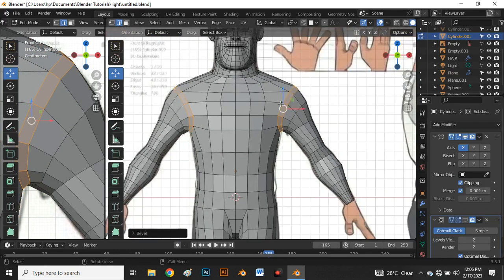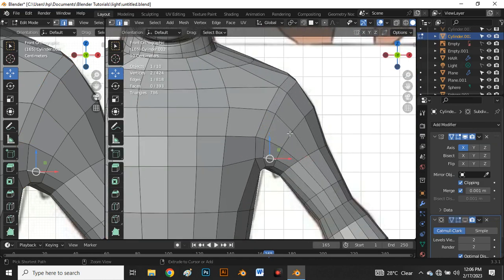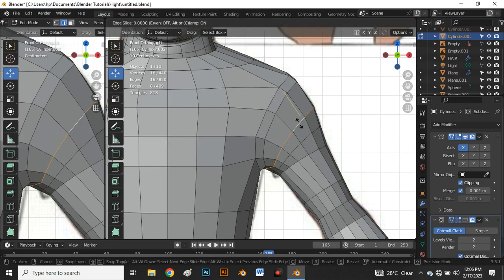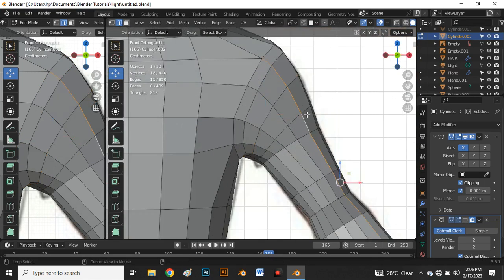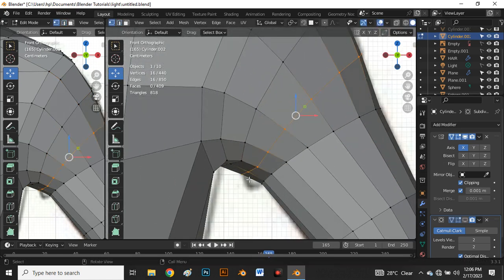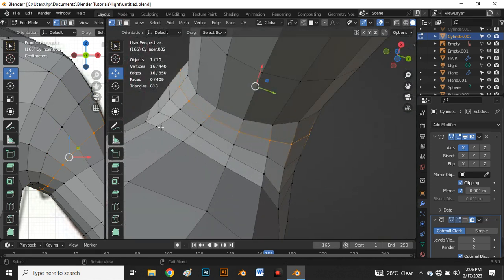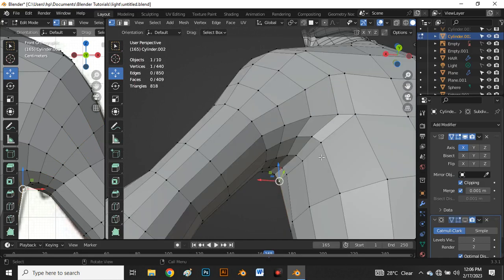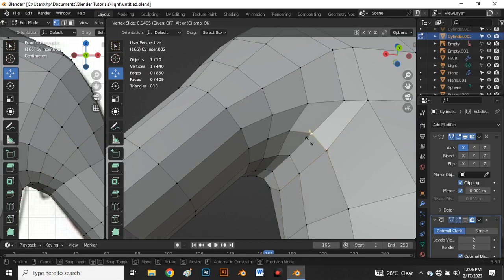have a demarcation of our shoulder here, which is nice. Of course, Ctrl R again to add one loop here. Hold on, select this loop and say G twice to move. And hold on, select this loop and say G twice to slide. See 1 for vertex selection. So now we can see how we can work on our character armpits here and see what we can move downwards. And G twice to move those vertices.